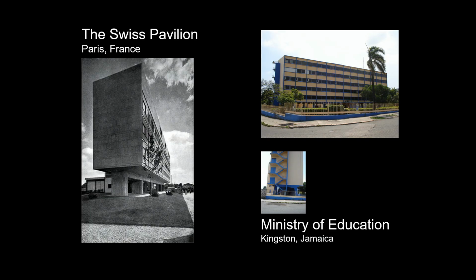With respect to the international style in general, and the Swiss Pavilion in particular, Christopher Arnold identifies irregular configurations as a 20th century problem and describes a number of characteristics not present in older masonry buildings that have led to poor seismic performance, as has been outlined by the previous speakers, including the 5 points of architecture. The building on stilts, or pilotis: without fully understanding the seismic implications of vertical structural discontinuity, designers often create soft or weak stories, as was elucidated by Tony earlier.